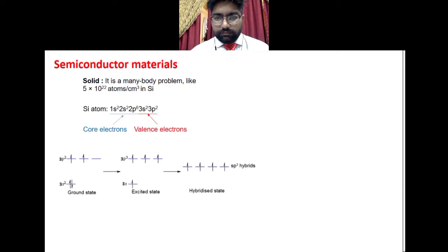Similarly for devices; this was for the material. For devices, it will alter the behavior of the device. If you want to find out the PN junction characteristics, but you have a non-ohmic contact, then your PN junction characteristics will not be revealed properly.